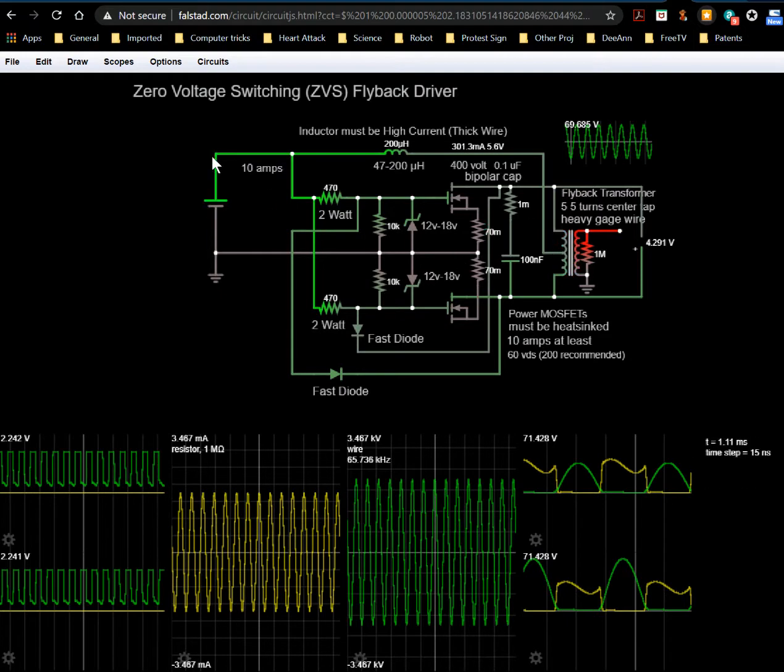If you just think about this battery being shorted across this terminal and this terminal, this inductor has 24 volts impressed across it, right? Let's say this is positive and this is negative. Because of that, the inductor itself forms its own voltage, a back EMF of 24 volts, which prohibits current from flowing.